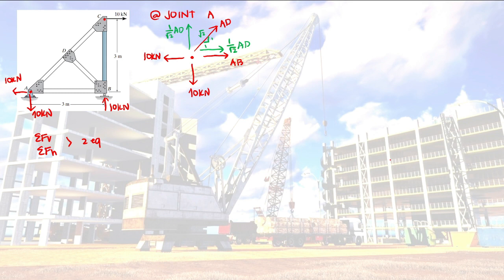Now, which to do first? Vertical or horizontal? We can start at summation forces vertical first, equals 0, upward positive. Why vertical? Because you see, in the vertical, AD is the only unknown. Now, if you do horizontal, how many unknowns do you have? AD and AB. So, it is much better for you to do vertical first.